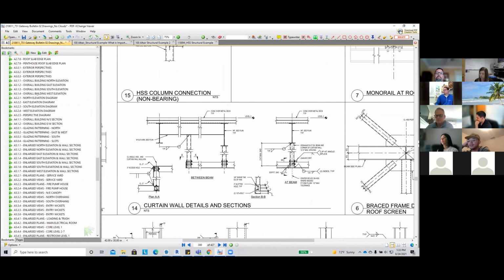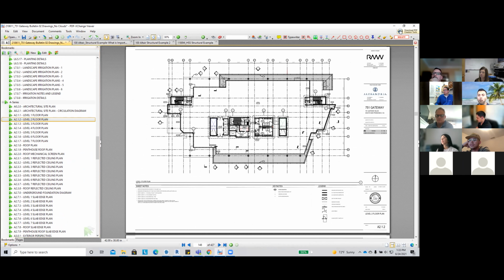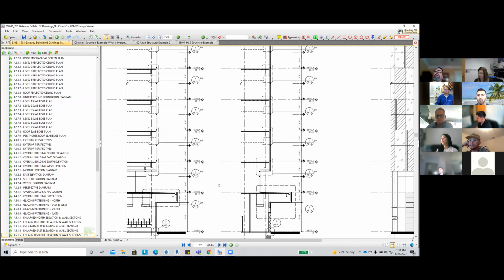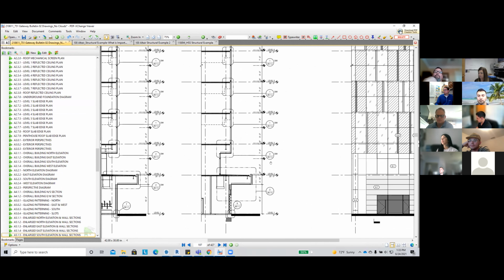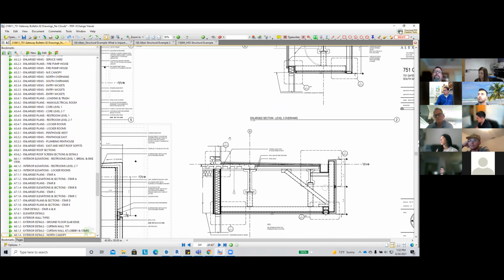So I think that's a huge one, especially anytime we're wrapping steel or cladding steel, that we pay really close attention to what the structurals are showing, and if we're varying from it at all, we should RFI it. Agreed. And I think too, once the drafter puts verify on there for their convenience, it's a note, and they're thinking, well, somebody will verify this. And then we go through all the submittals, nobody says anything about it. We assume, well, it's verified because no one said it wasn't right. But then no one confirmed it was right. So it'll always come back on us. It's never something we can go back and say, well, you didn't mark it up.